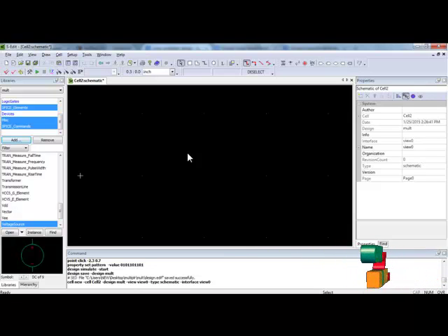From wherever you run, the output timing diagrams will show in W-Edit. In W-Edit you can see the waveforms obtained for the corresponding CMOS design, and also you can see the result parameters and measure all the parameters which you need for the design from W-Edit. Thank you.